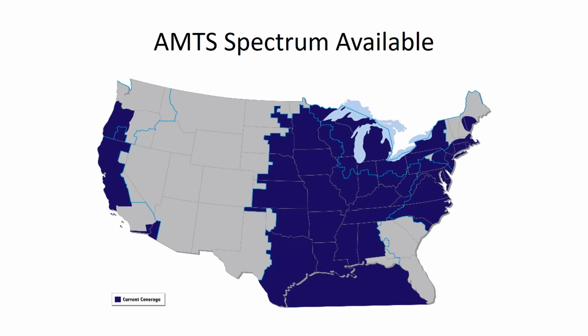The specific question they were asking was around antennas and being able to have adjacent license holders, one county over from the next. Yeah, so, and I'll let Bob answer this after me, the AMTS rules allow for a 20 dBu interference contour.